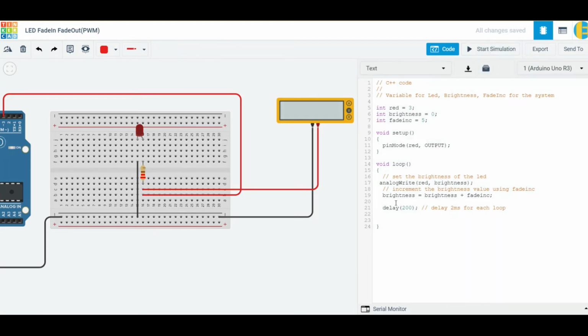So in this loop we are setting the value in the beginning to 0. But if we want our brightness to go to the maximum value, then go down from maximum to minimum, then go from minimum to maximum again, we can add one more instruction here for the negative loop.